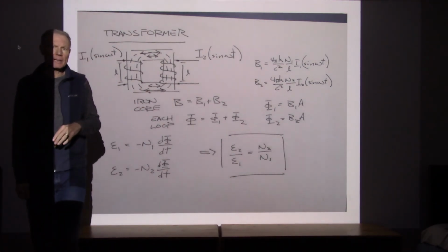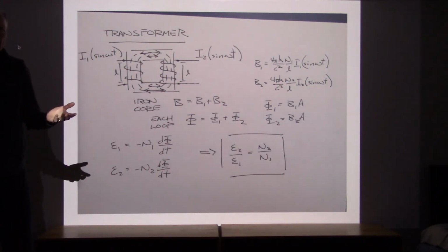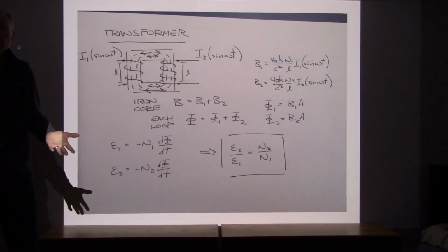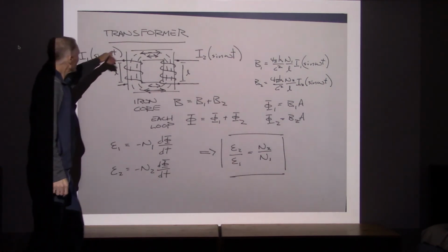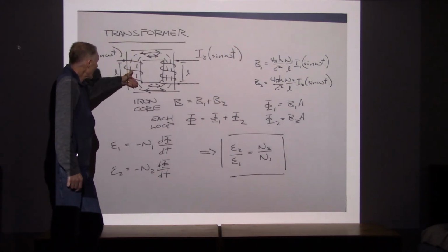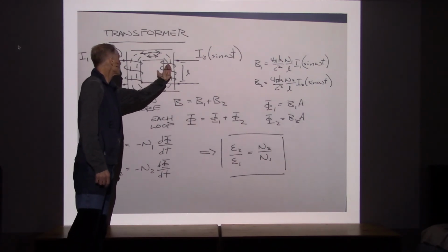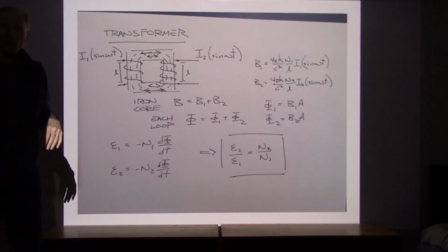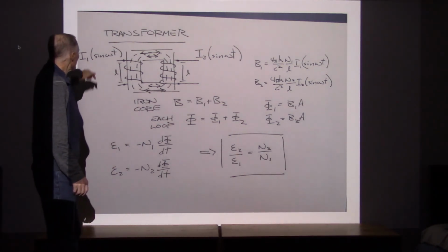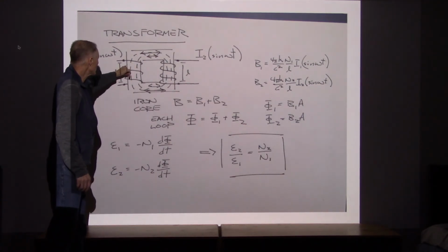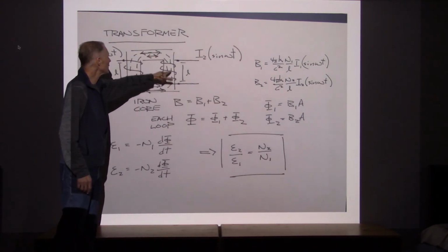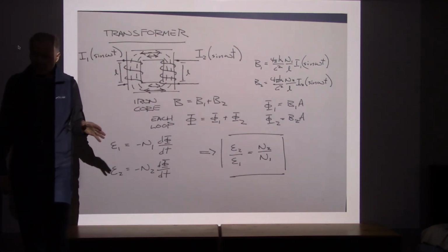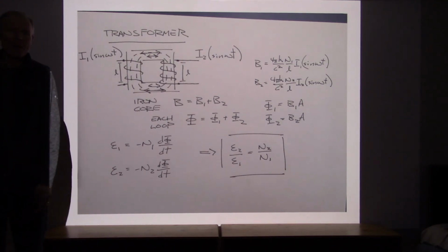Again, we're using those spinning electrons. So electrons don't mind this. They're able to realign themselves without a lot, we don't have to invest any energy in doing this. So we can set up the magnetic field here, and these electrons throughout the iron will align themselves with a particular orientation. Now, if it's direct current, then a constant current here sets up a uniform magnetic field inside, and if I have a constant uniform magnetic field on the secondary side, that doesn't create an EMF.